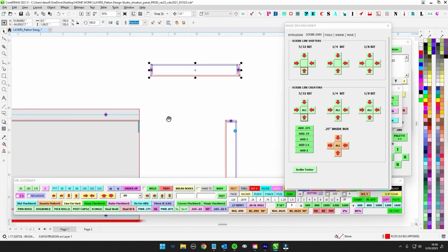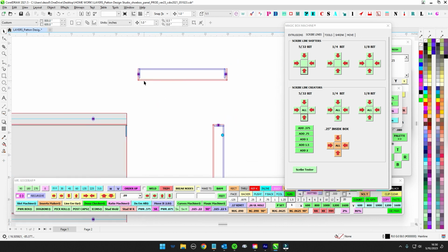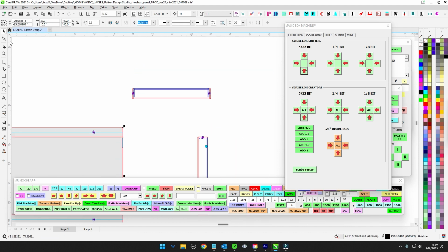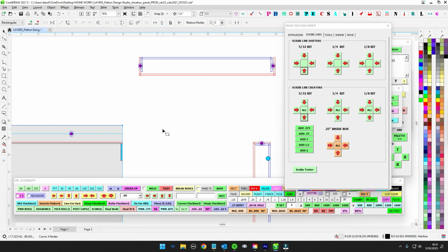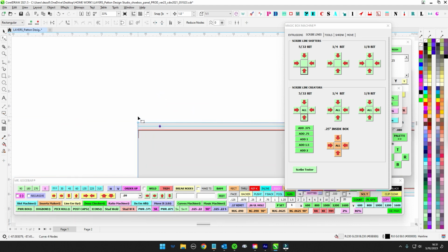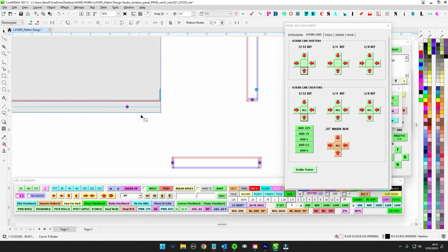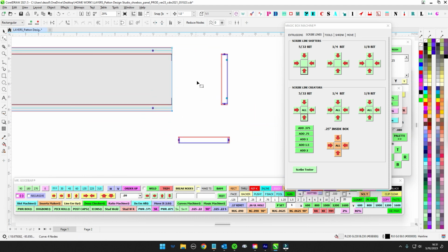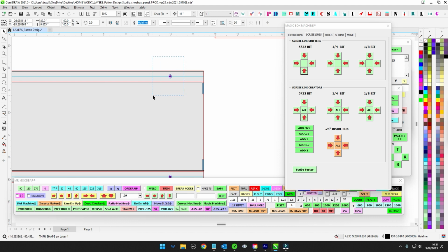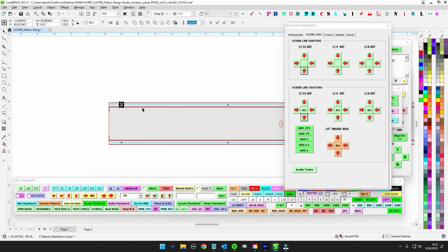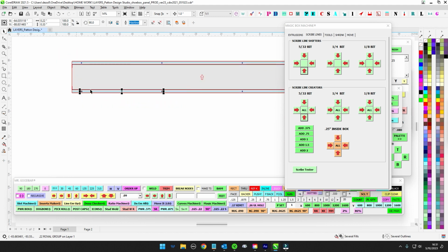But if it is priority that this thing stays to 1 inch exact, then you have to do what you just did on the backer. You have to bring this in a 1/16, and you have to bring this in a 1/16, and you have to bring this one, and then you have to bring this one. Okay. And then you will have to adjust your mounting hardware as well. So you bring those down a 1/16, and you bring these up a 1/16.